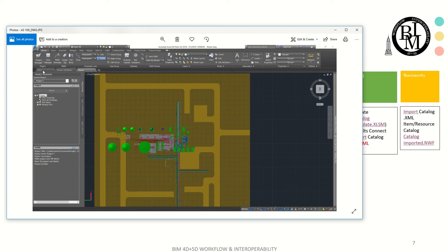But sometimes you might need extra metadata, extra properties. Then where do you go? In this case, you will be going to Data Manager here and export that extra information about the size of a specific area or some components that was not included in the DWG file format.